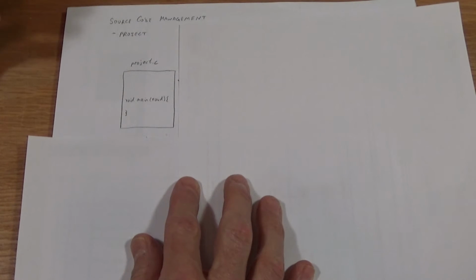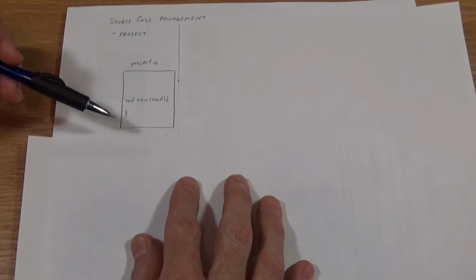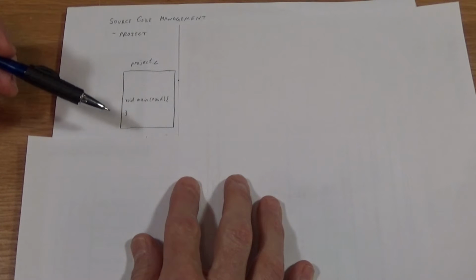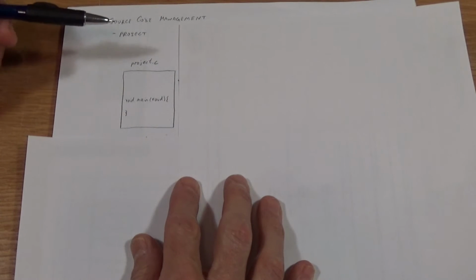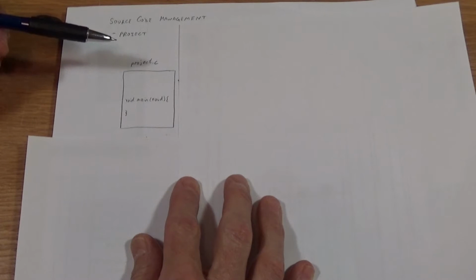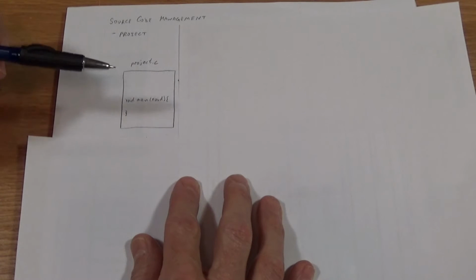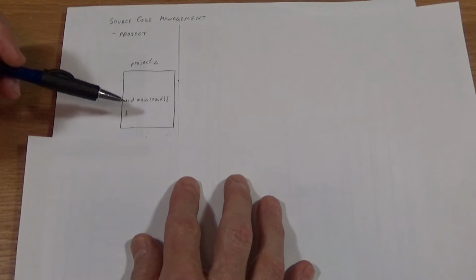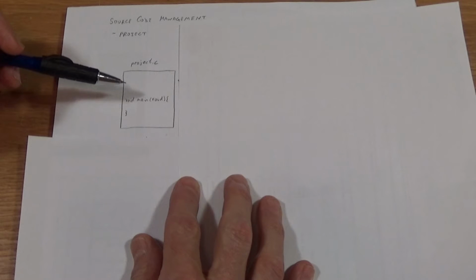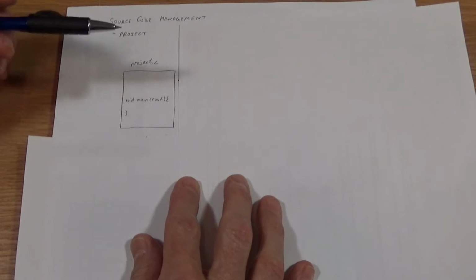Now, a project like this data logger idea is going to get quite complicated. There's going to be a lot of code. There's going to have to be some way of communicating to the accelerometer and the pressure sensor and the temperature sensor and the display and so forth, and the GPS unit. And each of those has a different kind of serial interface, and so you'll need to write software to operate those different types of serial interfaces that are inside the microcontroller, and to get it to communicate with your main routine to get the data out, etc., etc.